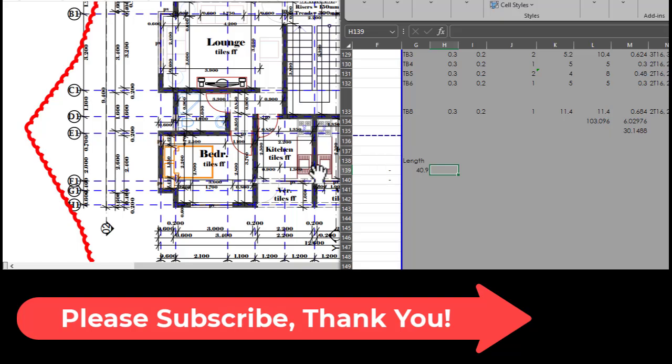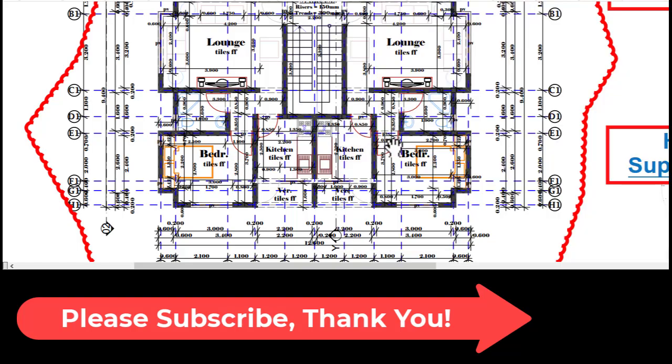So once we have that, then what we have next is now to get the area. Alright, so when you have your total length, the area is now the easier one, because from the length you just need to get the height, the ceiling height. That is now from the finished floor level going all the way to the soffit. Okay, to the soffit of the beam to the top. So we just need to get our section right. We get our section from which drawing it is, read that particular height, and then you'll get your area.